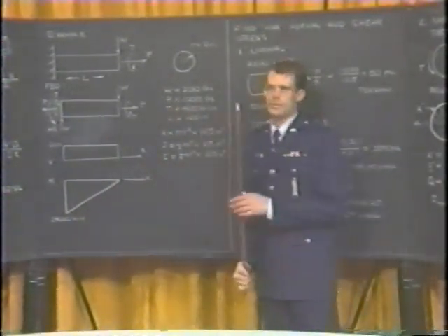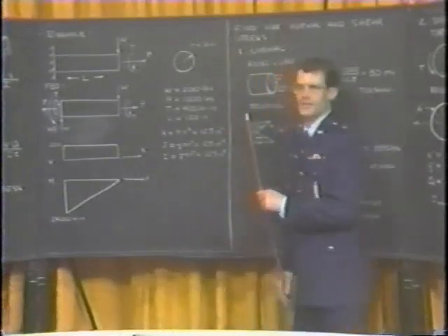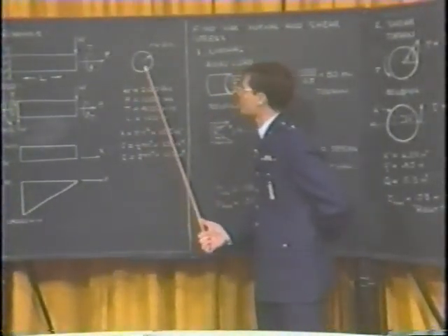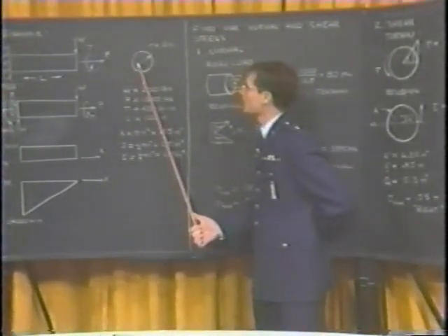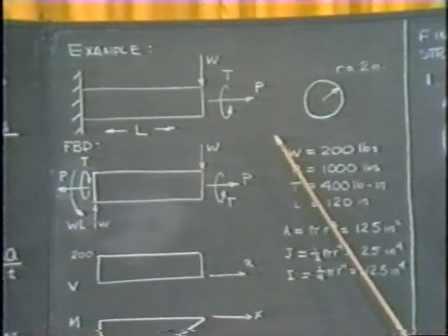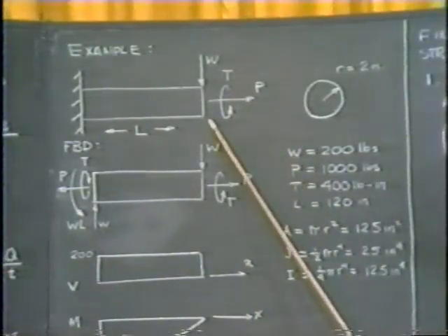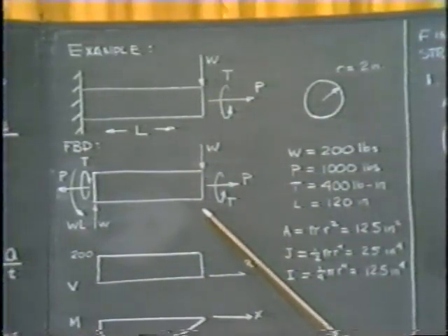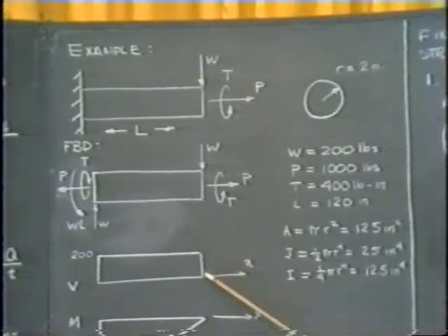The maximum shear stress, let's compare it next. You recall that the shear stress due to torsion will vary throughout the cross-section. The shear stress due to the bending load, W, will vary throughout the length and the cross-section. We should be able to tell where the shear stress would be maximum by looking at the shear diagram.